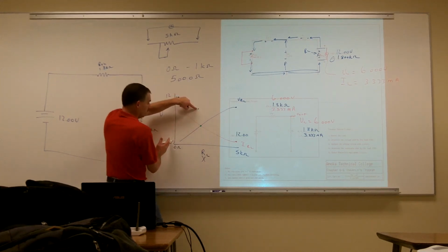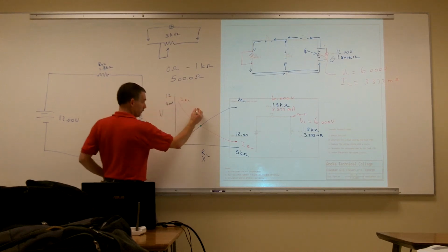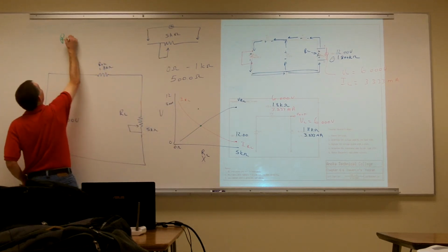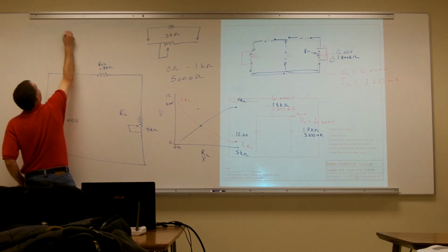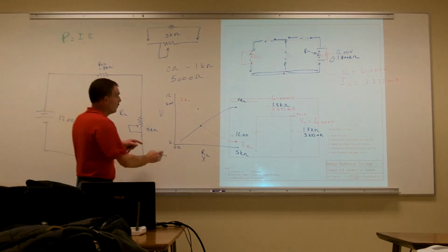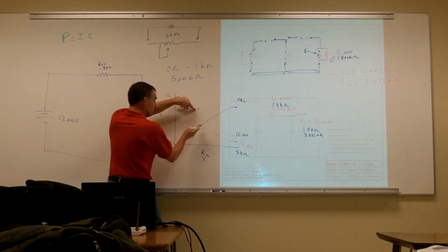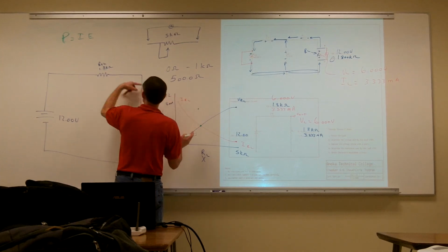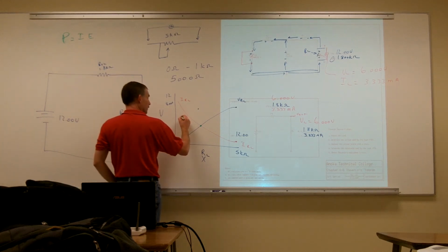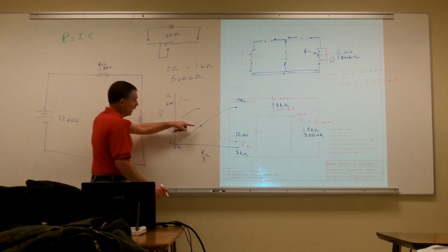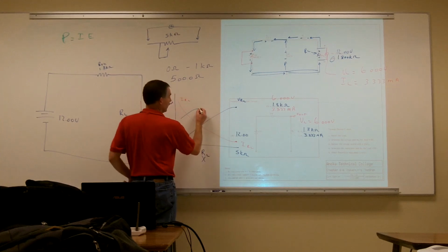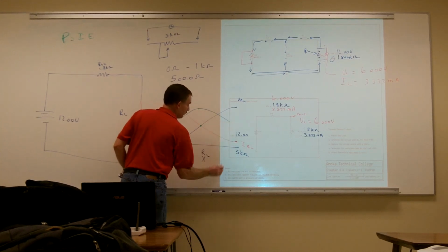At this point here, if I go from my 0 ohms to a particular number, I'm not going to have as much voltage, so remember that my power is equal to IE. So my voltage has dropped. Even though my current went up, my voltage dropped more than what my current increased. So my power is going to be kind of low on that point. As I hit that peak power, then my voltage goes up, but then I lose my current. And so then I'm going to start losing my power again.